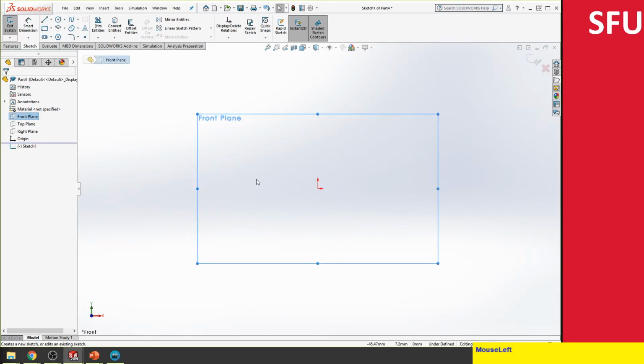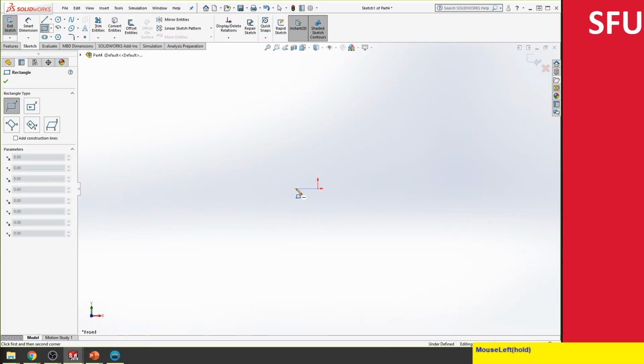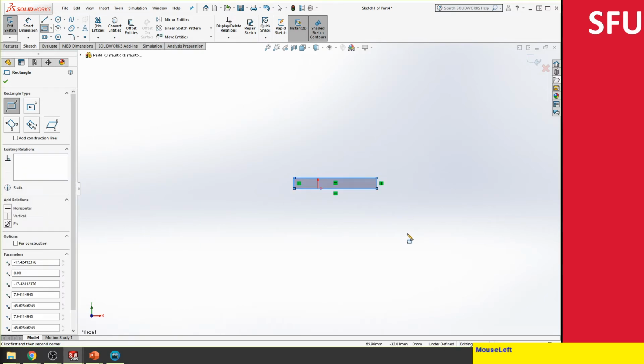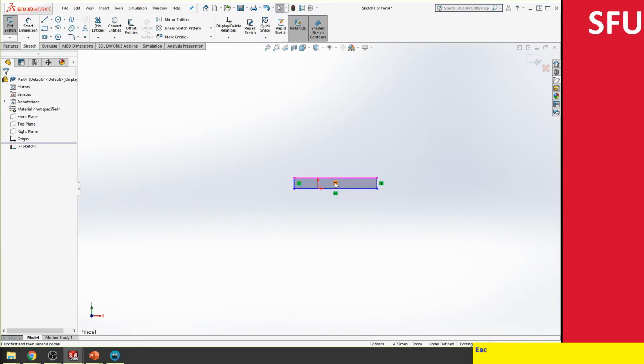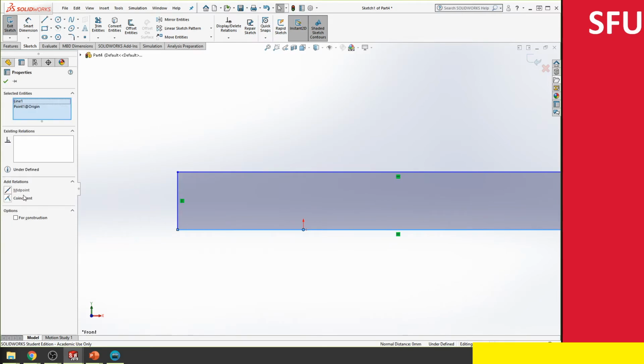So we're going to go sketch, and then we have the rectangle. So in this case, it's going to be a corner rectangle. So I can click, I don't actually click, move my mouse very close. And then I can maintain the constraint over here and then do it as such. So zoom in. So what I'm going to want to do is click on this point and then this line, and then see if you get something more interesting. So there seems to be like a midpoint constraint over here. So let's click on the midpoint and then see what it does. So you notice that it's now symmetric about the origin over here.